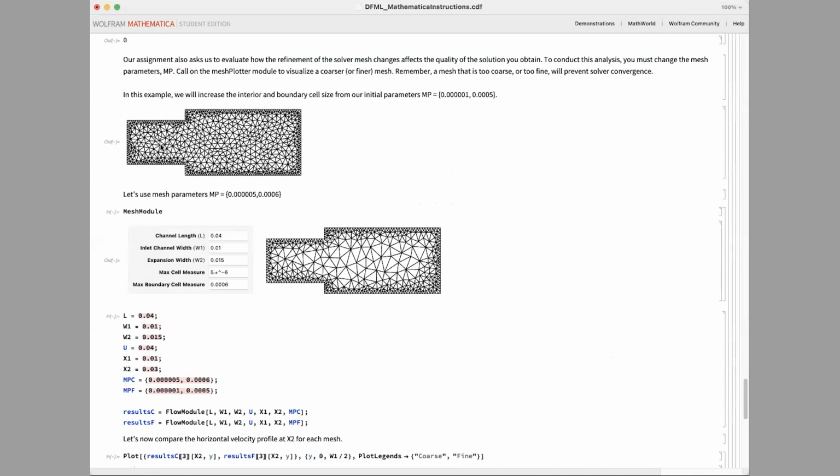We're saying we want to know the flow field and the pressure field at all of these places, and we're giving the solver an opportunity to make less guesses about what's happening between our points, because we have so many more points so much closer together. Here we're hanging NDSolve out to dry, and we're saying there's a lot that could happen between these points.